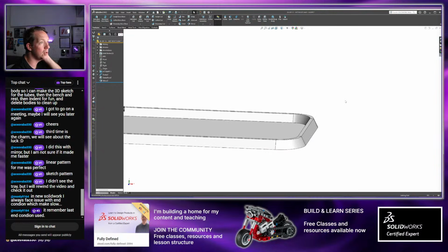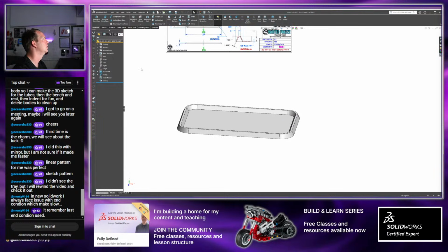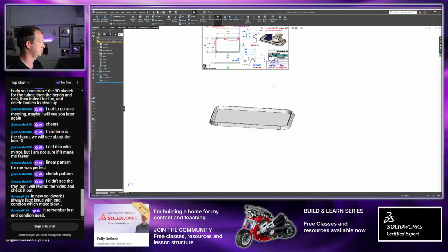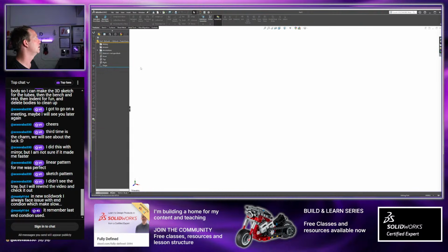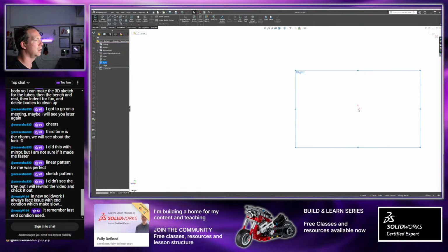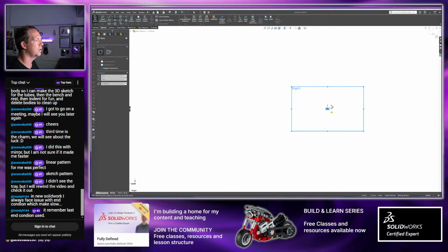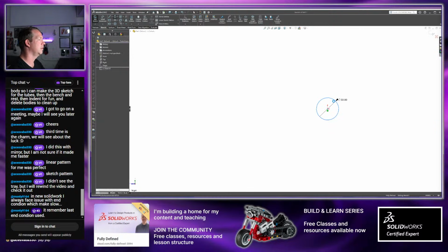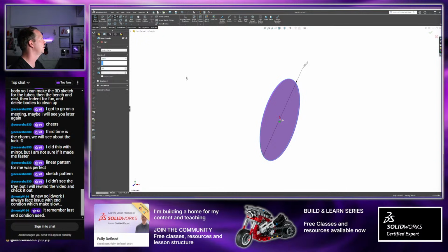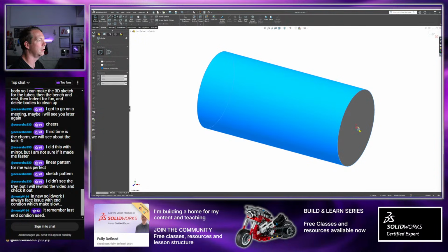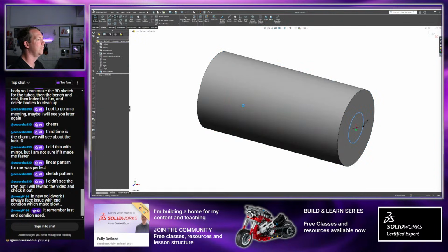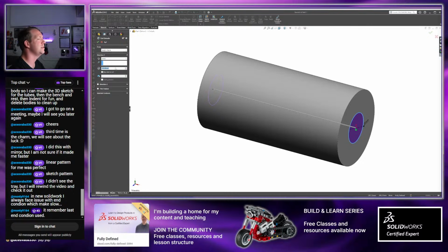Yeah, I think for most people that are experienced with SolidWorks, that just becomes second nature. If you do an extrude and you do a certain distance, you just get used to it. Here, I'm trying to show: if I'm extruding this 100 millimeters, and then I'm starting a sketch here and doing a cut, it's going to have 100 millimeters in there.